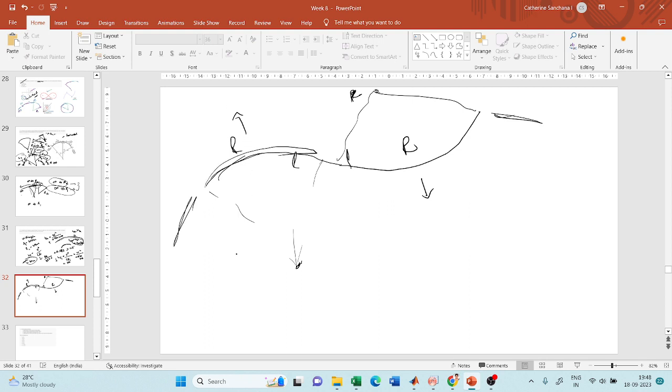Since it is pulling this vehicle outwards, its super elevation will be in this direction, the raise will be in one direction, say the left direction. Now, when you come to the opposite direction, the vehicle is pulled in this direction, right? Your vehicle will get lifted like this. So, in order to take care of that, the super elevation will be in this direction. See, it is in the opposite direction, exactly opposite. Here it was on one side and here it is on the other side.